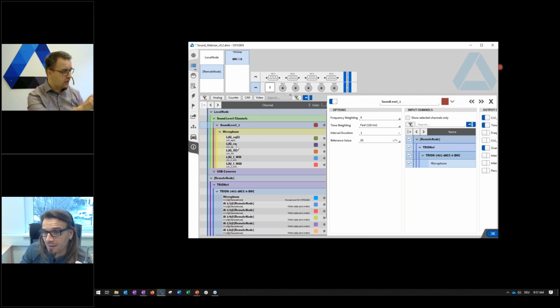Okay, just a question. I see reference value you said is included there as well. Isn't it always the same reference value as in the calculations we saw, always the 20? Why is there now a 1 as I can see as well? The 20 micropascal are always the reference value when we talk about airborne sound. So when the sound wave is transmitted through air. When we talk about waterborne noise, so about the sound propagation in water, for example, for maritime applications, there is a different reference value because the characteristics of the ear is different in water. And there the reference value according to the standards when you use a water-based sound pressure level is 1 micropascal. That's the reason why there is 1 micropascal.